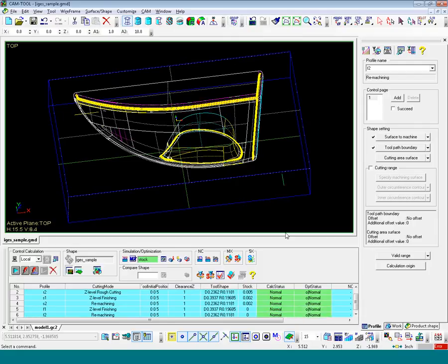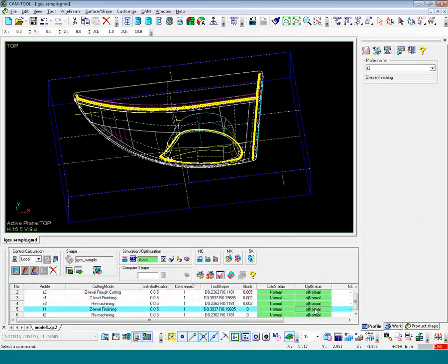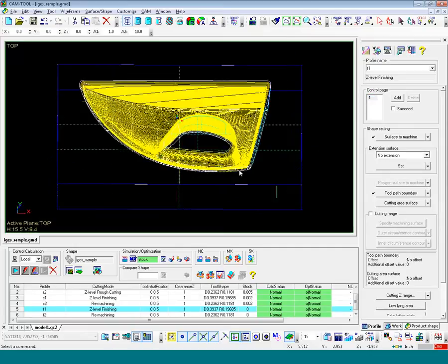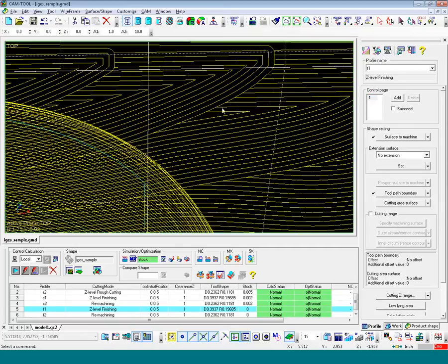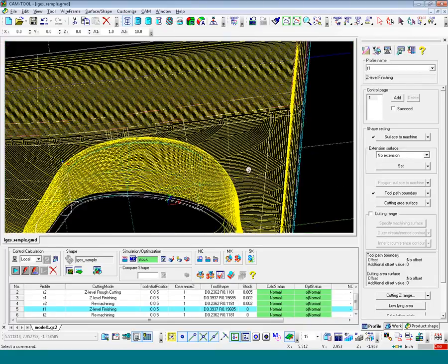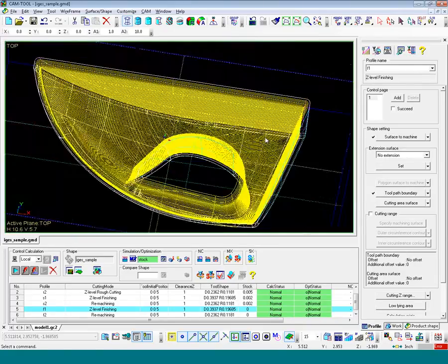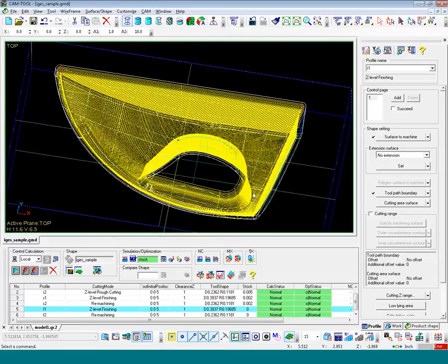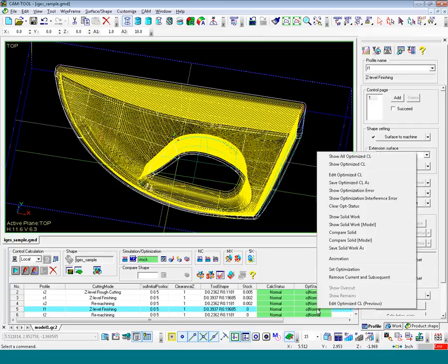Okay, so our toolpaths have finished up now. Now what we're going to do is take a look at them. The Z-Level Finish first. And we can see, if you look inside, where it's putting in these extra passes in with the scallops to make it a more true mirror finish in the bottom. So it's not stepping over quite so wide. But let's take a look at the stock model of that. So we'll click on it, right-click on the normal, and we'll say Show SolidWorks.